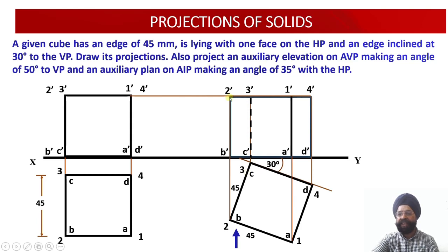Whereas the edges 2 dash, 3 dash and 3 dash, 4 dash are part of the boundary. There are 2 more edges joined with 3 dash, that is 2 dash, 3 dash over here. You see there is severe inclination over here. Even though this is going to be dotted, this is part of the boundary, so you cannot draw it dotted. The boundary has to be dark.